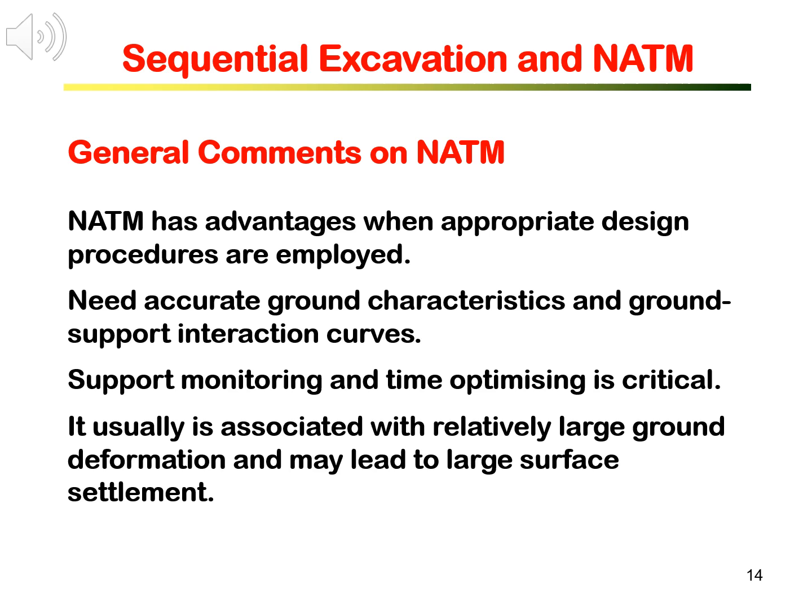In general, people recognize that NATM has advantages when appropriate design procedures are employed. For design, the excavation sequence and the support, NATM needs accurate ground characteristics and the ground support interaction curves. This today is primarily achieved by numerical modeling. Support monitoring and close observation are key activities in this excavation method. Time to react and time optimization is critical. NATM allows the ground to deform in order to minimize the support requirement. It also means that it will have relatively large ground deformation around the tunnel, and in turn may have relatively large surface settlement.